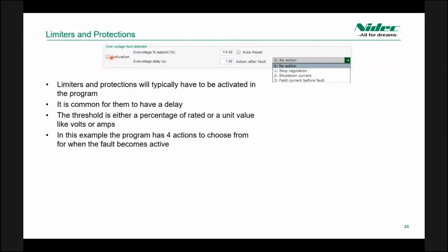The protections will have a delay period, since we don't always want the fault to be activated immediately, because it is common for set points to be exceeded for only a short period of time and will be corrected within a reasonable amount of time. The fault threshold will be a set point either based on the percentage of the set point or the unit of the set point being monitored, like voltage, current, or temperature.